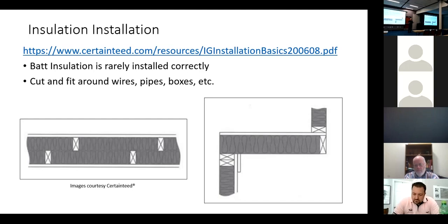You only want the air barrier on one side, not two, because you'll capture condensation. Air barrier, not vapor barrier. We'll talk about vapor barriers because I have an issue with them too. They're never installed correctly, and the drywall guy comes in and cuts holes in it, and I think they do more harm than good. That's an attic. Never have an air barrier.